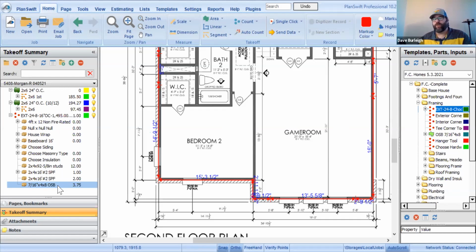What we want to watch for is that a lot of times we're seeing lumber yards are really good at using kind of vague terms. They love calling things a 5-stud corner. If we asked you how many studs are in a 5-stud corner, the answer is going to be 5. In reality, the answer is only 3 because 2 of those studs are already accounted for when we counted our walls because we know we have studs on every wall.